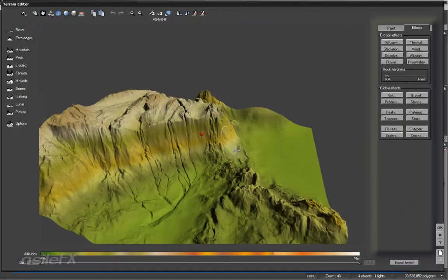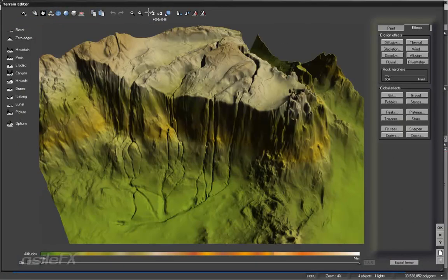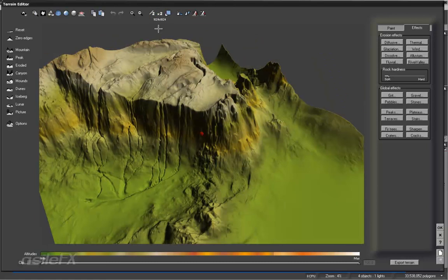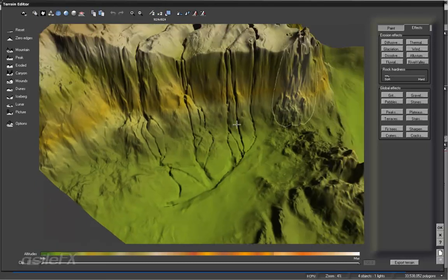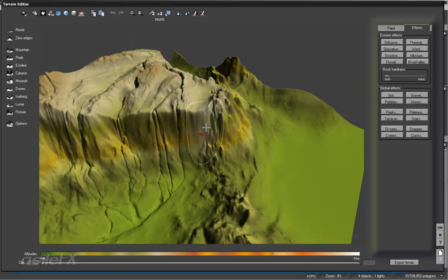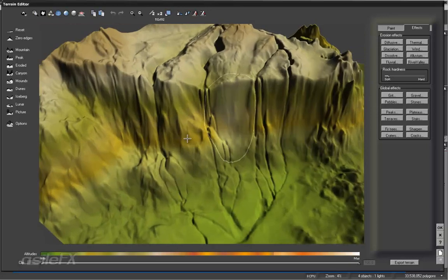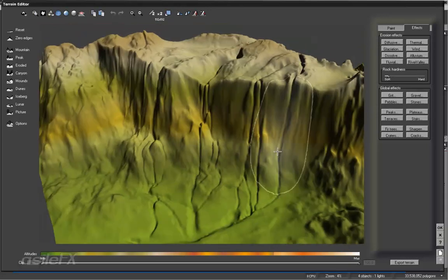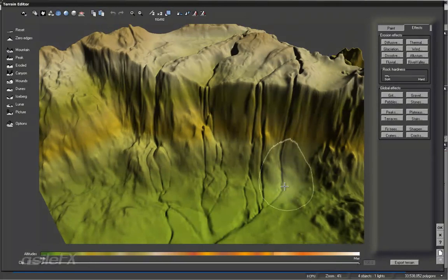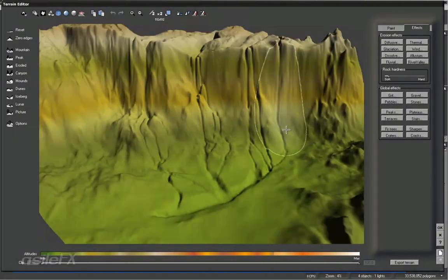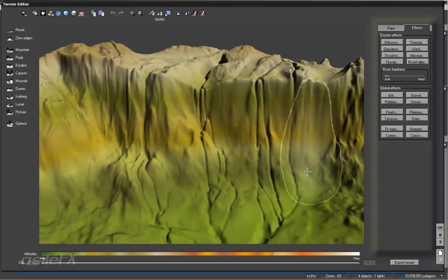So what I'm going to do is downsample the terrain, the standard terrain, not the procedural, and bring it down to 512 by 512. So a lot of smoothing overall throughout the terrain. And once we load the image in, even though it's a much higher resolution, it will create larger areas rather than sharp peaks.